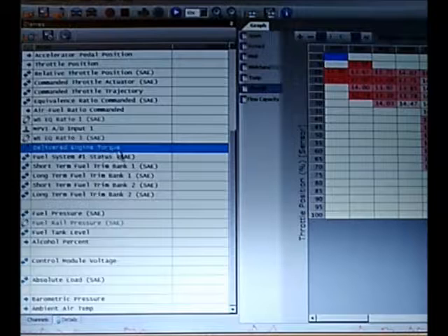Delivered engine torque. This is what I used to filter the results so that I wasn't getting garbage data that belonged to the decel phase. So delivered engine torque, you want that to be positive. You might pick a different number other than 0. If you want it to be truly accelerating, you might pick a number like 10 foot-pounds or greater. But I just picked 0 because I wanted to pick up all data that wasn't literally decelerating.